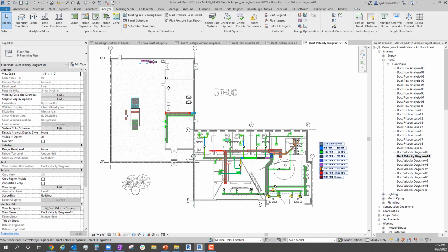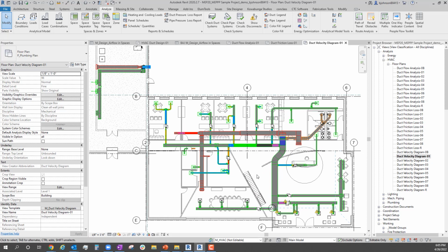But here I have these visual representations of views that tell me exactly what's going on, and within a range that I'm working in, trying to figure out, is there anything I still need to change in that view? So as much as I can, pre-size, run ducts one size, auto size once, check these analysis views, and I may have just solved 3 to 10 iterations from SD through 50% CD, barring any architectural changes, right? That's my end goal.